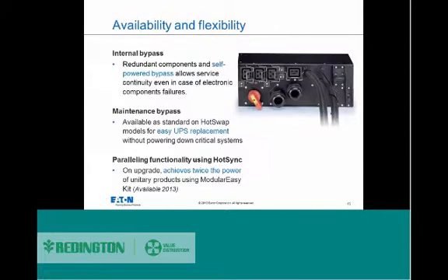These are some of the other features which you get with the 9PX. This is free of cost, which is the internal bypass. You have a maintenance bypass in case you want to remove the unit for servicing purposes. You can give the connection directly from your utility to the load without disrupting the connection of the entire UPS. So these are some of the features which are very critical and needed, and this is provided by Eaton on the 9PX models and the higher end three-phase models also.